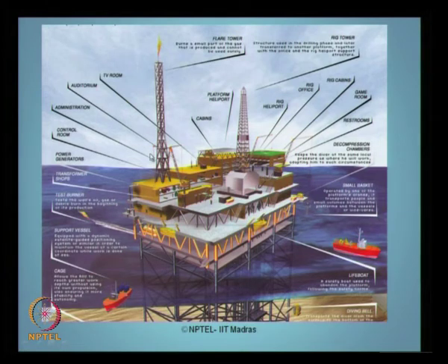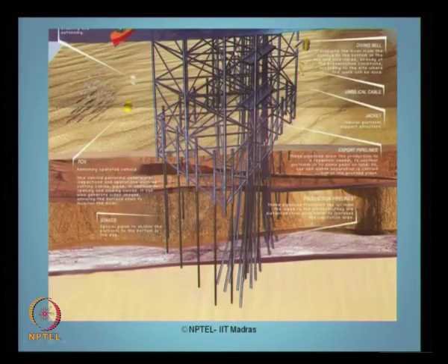This is what we call a flare tower or a flare stack. This is a rig tower which is used for drilling rigs. We can see the lines going down, these are all risers. In the next photograph you will see them in detail. These are all risers, these are umbilical cables. The blue line here is a jacket structure. These are all the bracings of a jacket structure, and so on.